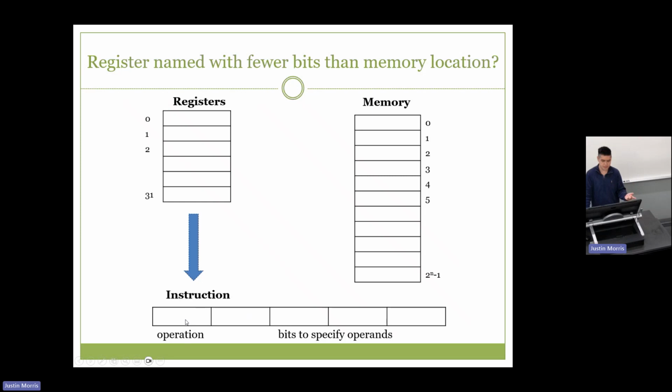But this operation could also be I type, which tells you that it's one register and one immediate. And when it's I type, the operation is also baked in here, so it has the combination for add immediate, subtract immediate, things like that. And then this field is the destination register, and here's your two, RS and RT, your two operands.